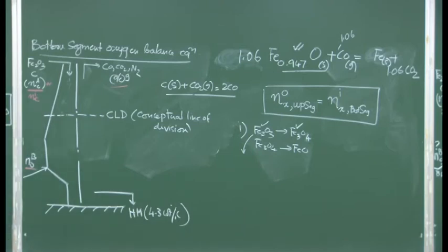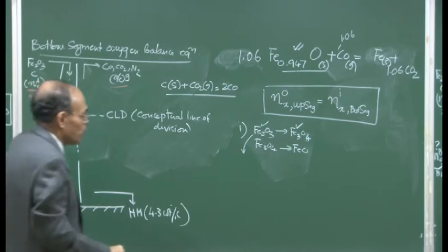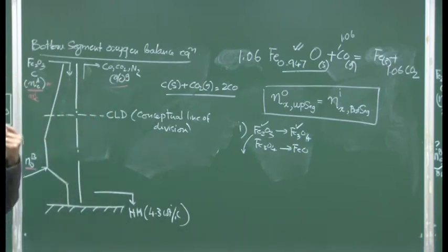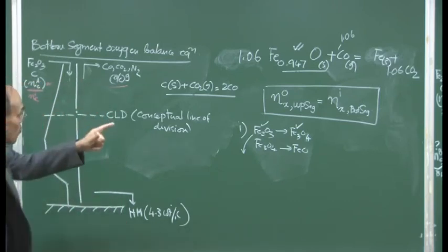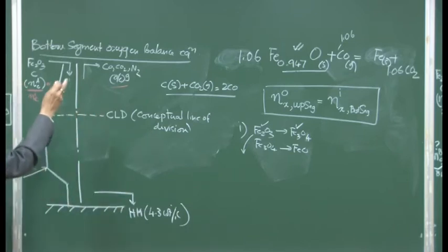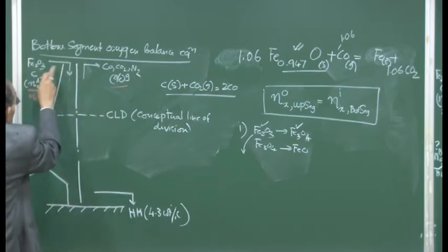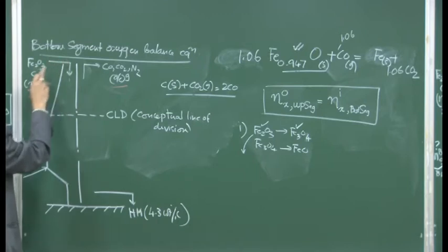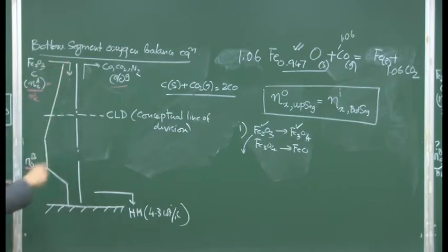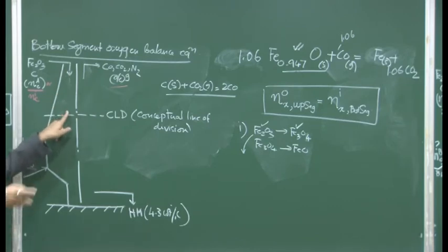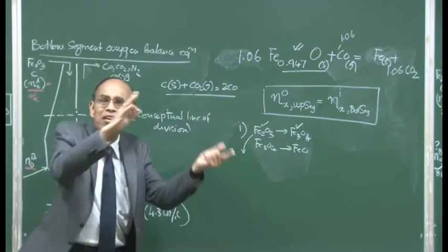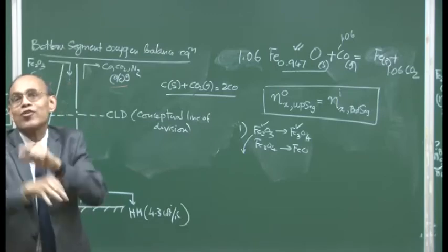If we now apply this hypothesis, a corollary comes out: whatever coke is charged into the blast furnace behaves as an inert species here. In this case, what is happening? Mere redistribution of carbon monoxide and carbon dioxide is taking place.